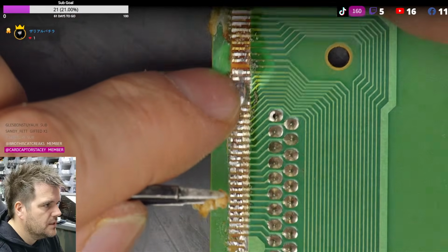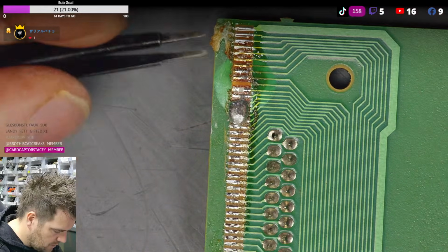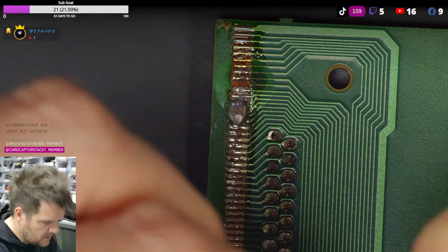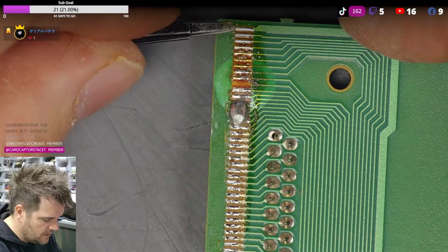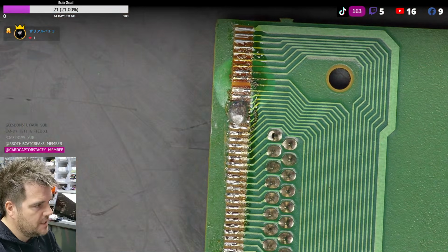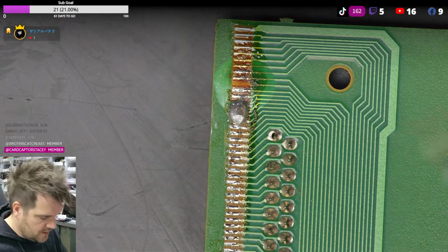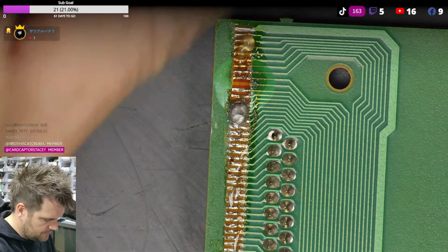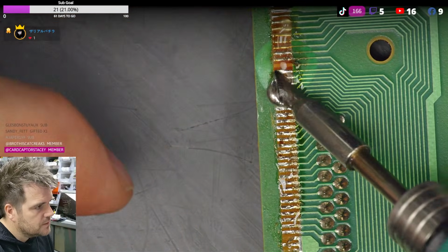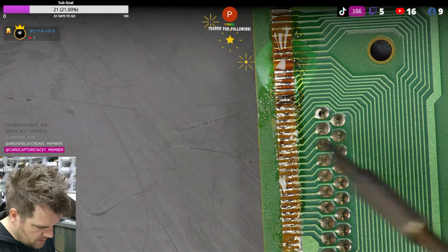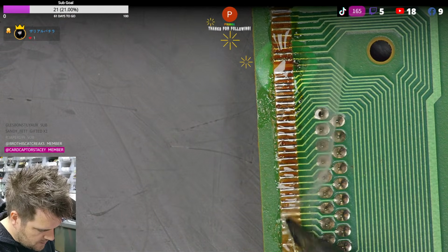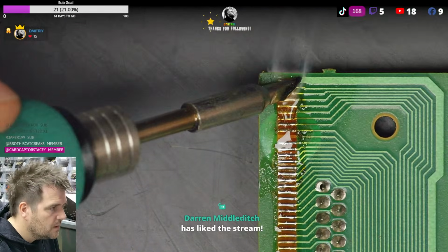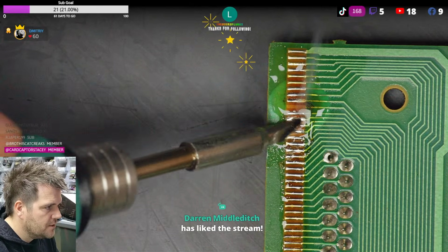Yeah, you can see as well, even that one's come off, so these are quite weak. We'll obviously restore them when we put the connector on. And they shouldn't really rip that easy. That seems to be quite easy that it's ripped, but it's no problem to fix that. So let's first clear off the excess solder. I will probably hot air this connector on. I'll see, because we have the cartridge connector the other side.